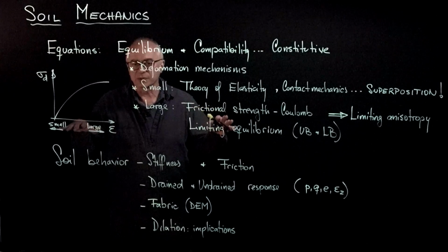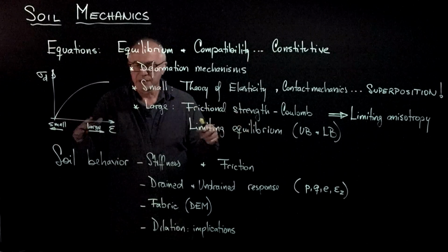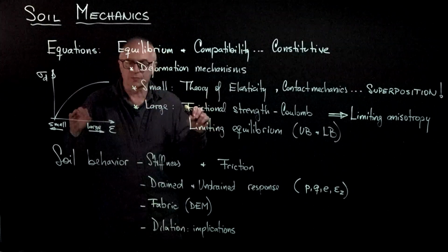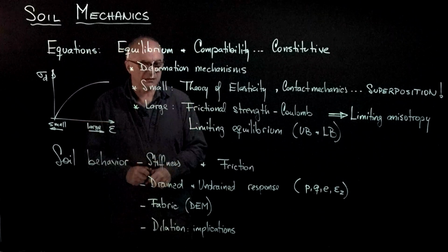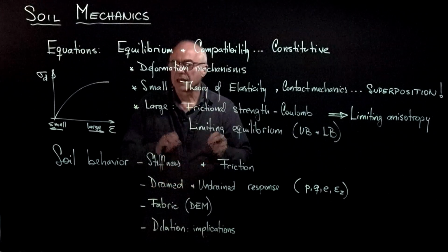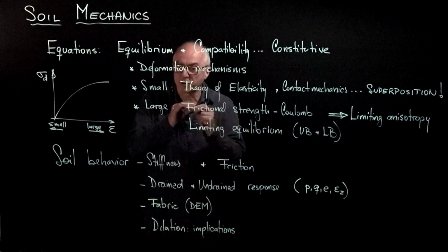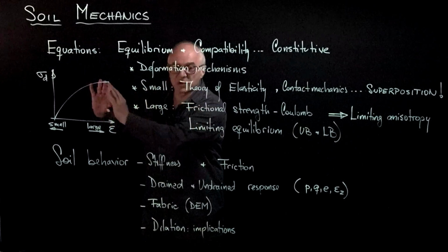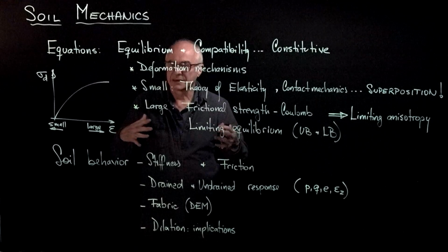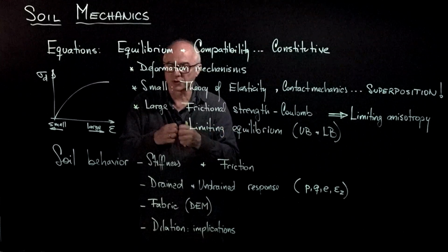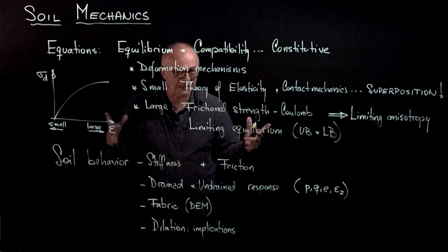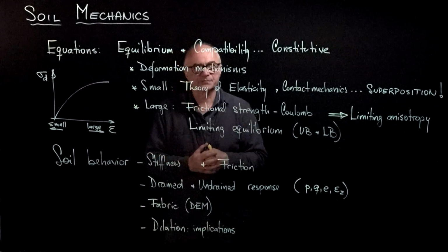Equilibrium conditions tend to be enough for a simply supported beam, but when we have too many anchors or limitations to movement, then equilibrium equations are not enough. And we need to also consider compatibility equations, whereby we assume that points that are together will remain together throughout the deformation. In other words, that there will not be a significant failure in the system from the point of view of parts moving away from each other, like when a concrete block breaks apart.